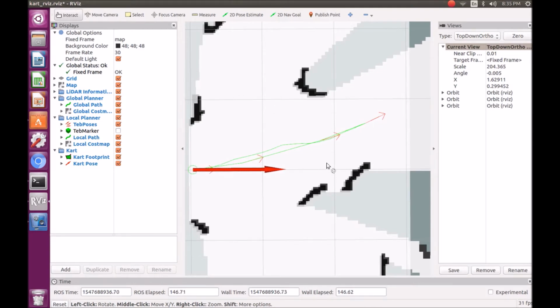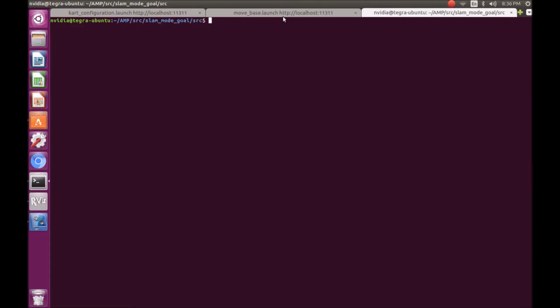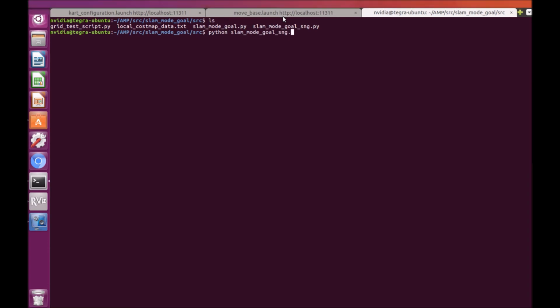One of the most important things I had to do in order to get to this place, however, was that the initial ROS navigation stack provides for a differential-like drive robot, whereas our cart is more car-like, where we only have a velocity and a steering angle. So one of the things that we had to do was to replace the local planner and use something called a TEB local planner, which converts it to Ackermann steering, or more car-like steering. And that's why you don't have really jagged curves. You have more of a smooth curve. And if we get rid of the global planner, this is the exact path that we need to take in order to get to this point.